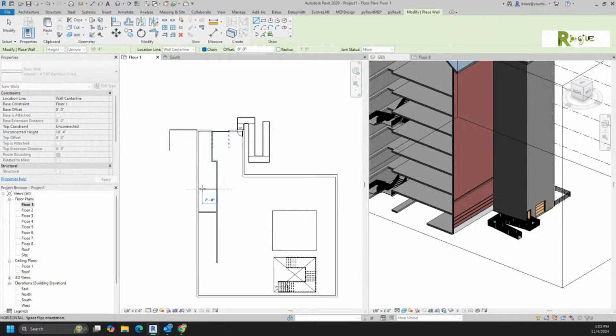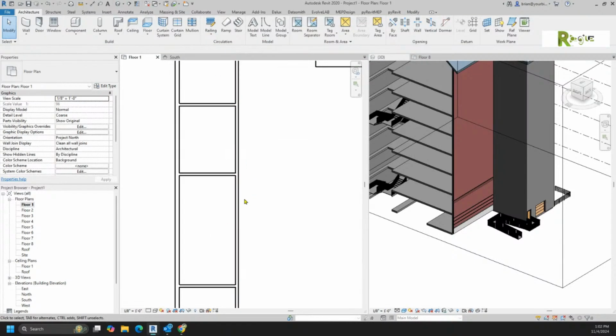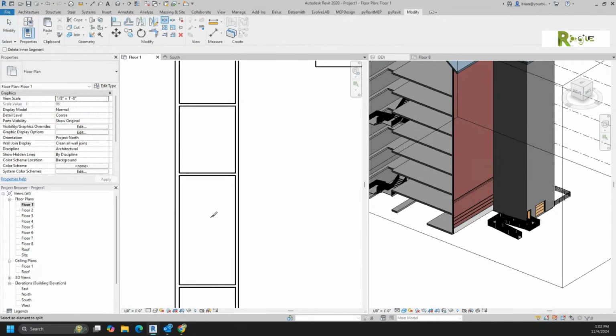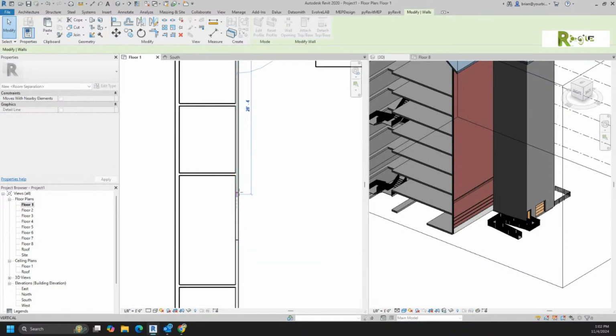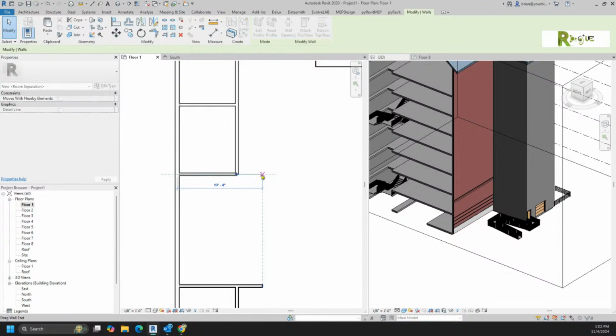And that's going to be a room. This might be a mechanical room, and this might be an office. Oh, and then I might say, you know what? I'm going to show you how I would typically do this. So underneath the modify, I would split this room. Notice how I just take that dot and I drag it back, and I take this dot and I drag it back. And then I might pull this one beyond and this one beyond. You see how they're lining up?